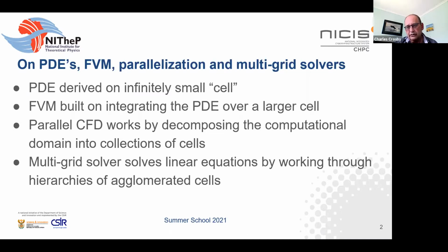And you assign the individual mesh blocks to individual processes in a computing cluster. They've got to be solved sequentially anyway, so you might as well solve them in parallel over many different computers. And at the end of each iteration step, the individual blocks communicate with each other and exchange boundary conditions.